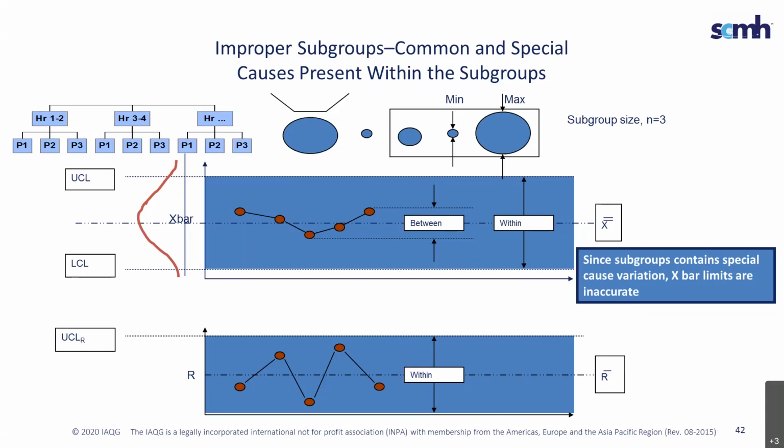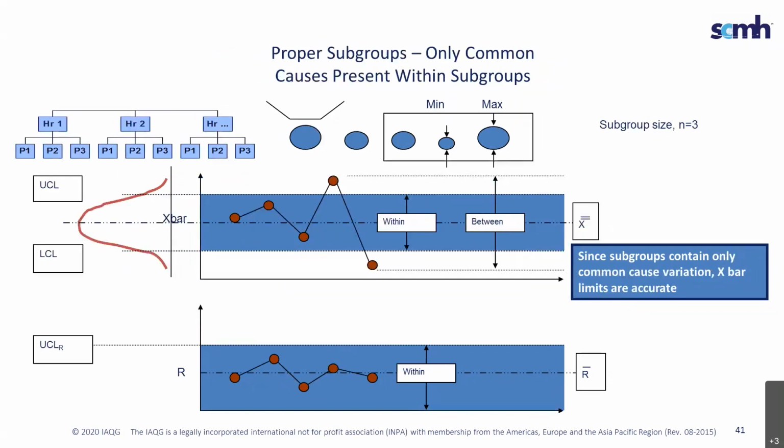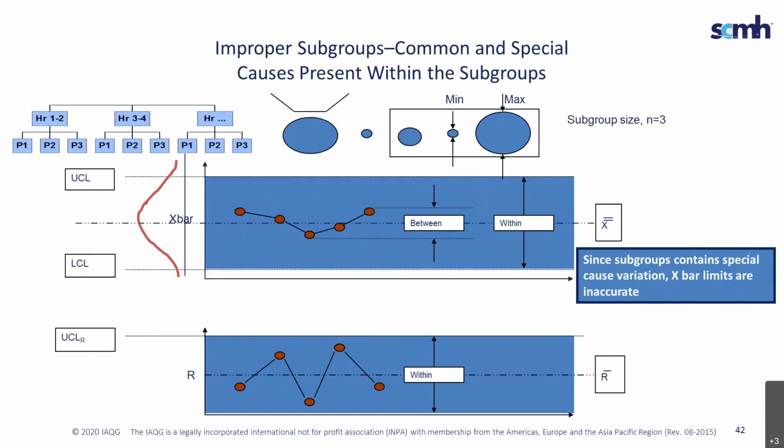And in this case, you'll see that, by the way, mathematically, behind the scenes, these are the same samples and the same numbers, but the variation is combined within, so therefore it looks like I'm in control, versus the previous one where I was out of control. Again, rational subgroups are making sure that it's common cause variation and not between variation. You have to make sure, because it could be a pitfall to under-control your process by putting too much variation within your subgroup size.